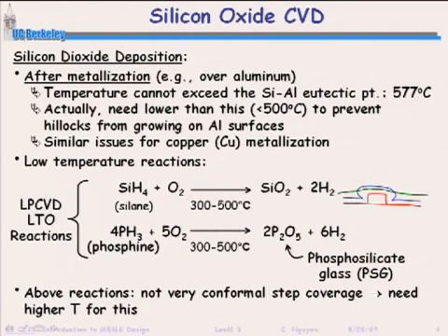In fact, sometimes you want to densify, so there's a lot of different temperatures. 1050 if you want to reflow very fast. Also if you want to dope other things with the phosphorus, which is a process I'll talk about later on. 950 for 30 minutes actually densifies the oxide into a very strong oxide. So what happens is, once you deposit phosphosilicate glass, it's not a very good oxide. It's got a lot of gaps and pores and that sort of thing. So you can densify it by just taking it to 950 degrees C for 30 minutes. You can also even reflow at much lower temperatures as well. So what temperature you want to use is up to you. It's just going to take longer if you do that.